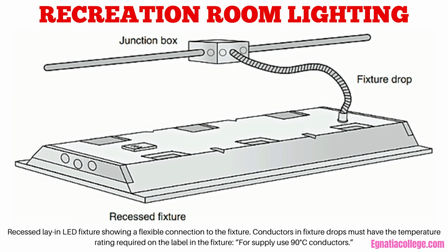Fluorescent fixtures of the type shown in this figure might bear the label recessed fluorescent fixture, which might also state suspended ceiling fluorescent fixture. Although they might look the same, there is a difference. Recessed fluorescent fixtures are intended for installation in cavities in ceilings and walls and are to be wired according to Rules 30-900 through 30-912. These fixtures may also be installed in suspended ceilings if they have the necessary mounting hardware.